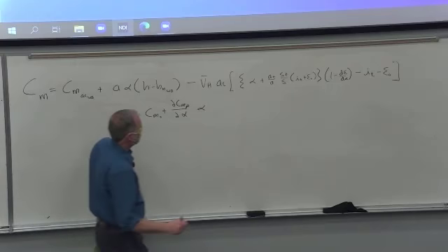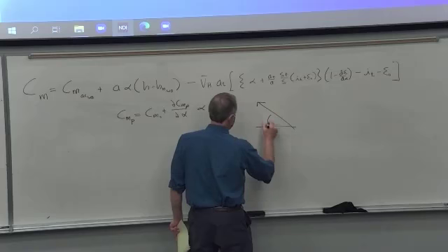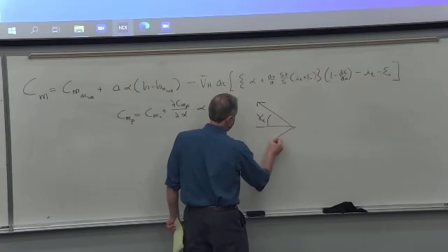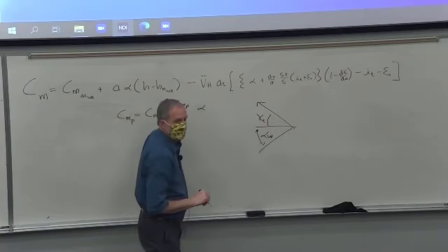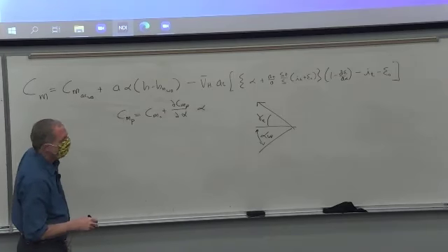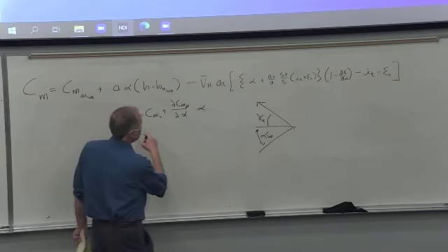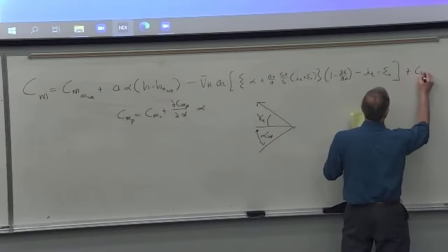If you remember, it makes sense because the thrust line was at an angle gamma of the engine, and then the angle of attack was here, so the component of the thrust could vary with angle of attack. It can change. So we'll just throw that in. So that's what we add on the end here as far as the propulsion stuff goes.